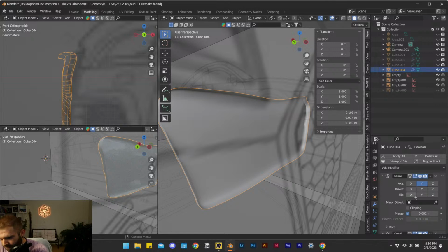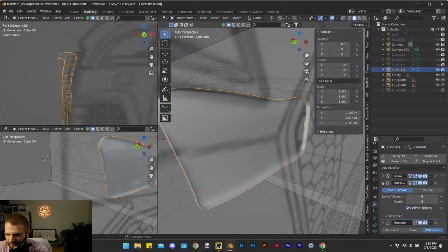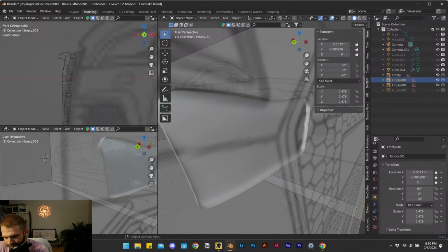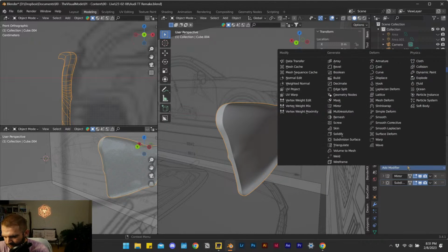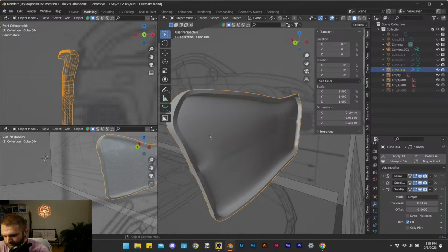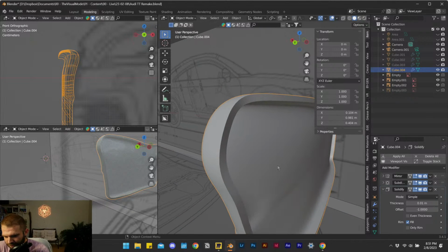And the solidify modifier we had applied before. Oh, we did not apply it to this one earlier. So let's start doing that so we see what kind of shape we start to get. So we can do solidify, and now we get a thickness going on it. I think that's thick enough. I'm gonna leave it at the default.